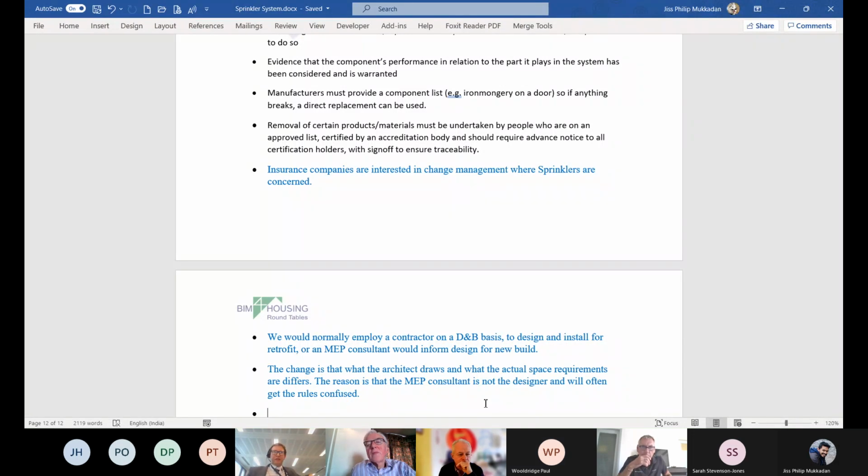Can I just add to what I think, Alan, you were onto there, is that the functional requirement of building regulations is that the outside should not cause fire to spread across it. And I think, as you say, the approved documents give you guidance on where that starts. Not to say that a building below it shouldn't be looked at in different contexts depending on what it's situated next to, the risk inside of it. This is where it becomes a bit difficult, so I'm sure the same sort of principle is on the sprinkler side as well.